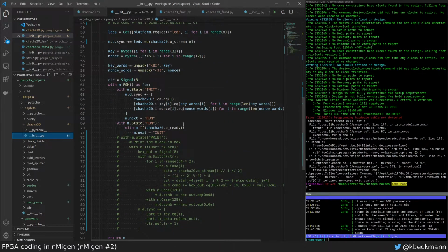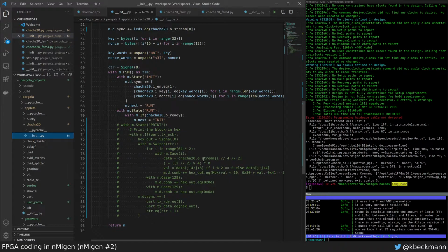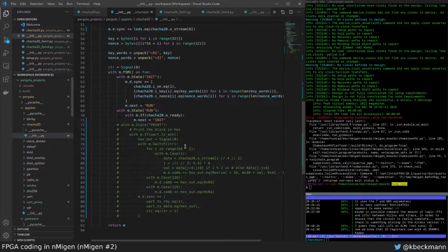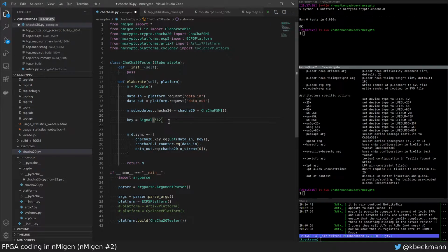So here's a bunch of commented out code, but essentially I had this long register that I'm picking out which byte to print. And that seems to generate a huge MUX tree, which is expensive, I suppose. So let's not do that and try to do something smarter. So here we have a key, which will be a bit register, 1 bit wide.